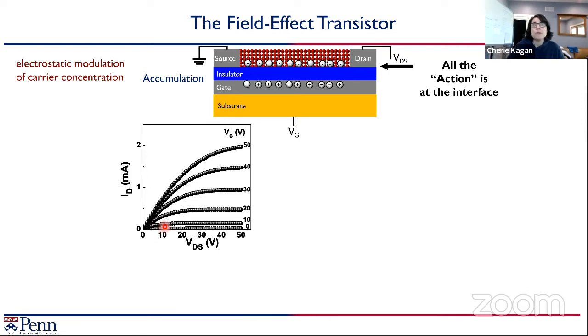Now, when we make thin film transistors, for anyone who knows transistors, we're typically operating in what's known as an accumulation regime, in which the carrier type that the nanocrystal layer is willing to transport, we're just accumulating more of those carriers. So often in a sample that is already a good electron transport material, if we apply a voltage that increases the electron concentration, we'll get a greater transport of electrons in the material.